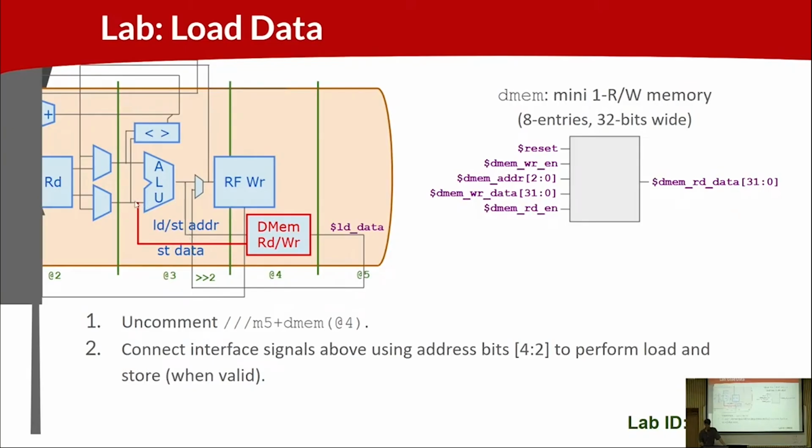You want to make sure that you're getting that after this mux, right, in case it was the previous instruction that wrote that register. If it was, that value is coming through this bypass path through the mux. And then, think through what's needed for the read enable and write enable.